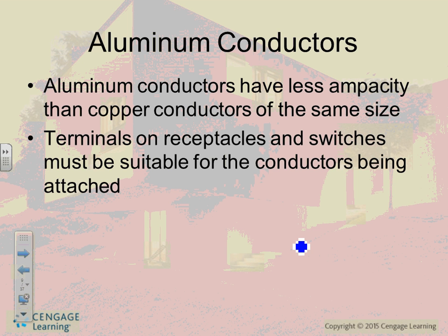That's why they don't want you to do the connection up in the air or inside the walls. Because if you have arc and spark, you contain the fire. You don't burn the building. And receptacle switches must be suitable.